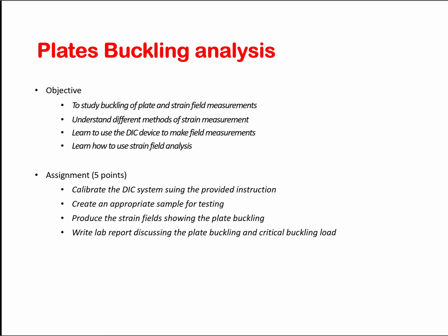So the objective of these labs is to study the buckling of plates and strain field measurements, to understand the difference between point measurements of strain and field measurements of strain. We also want the students to learn how to use a DIC device. DIC stands for Digital Image Correlation, to make field measurements, and we want the students to learn how to perform any strain field analysis.